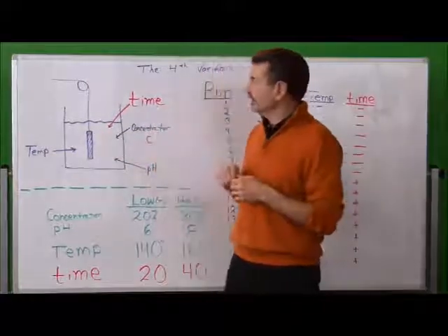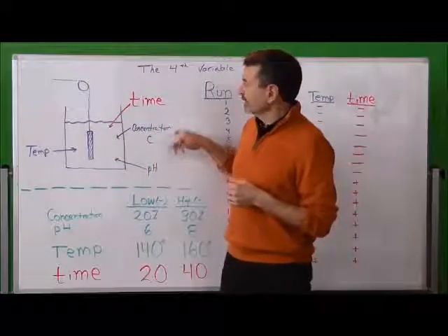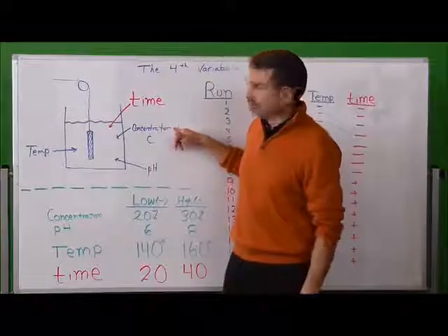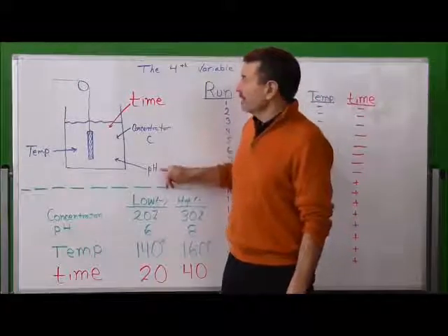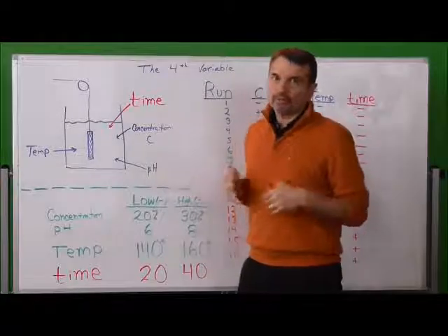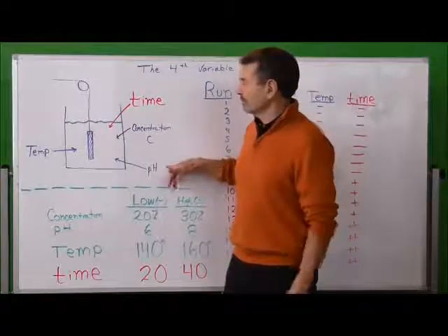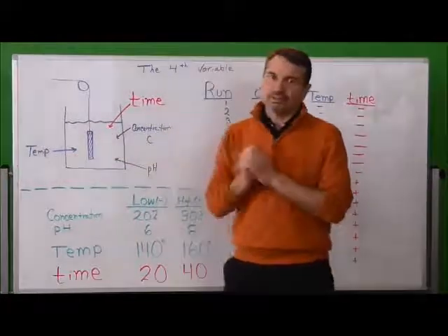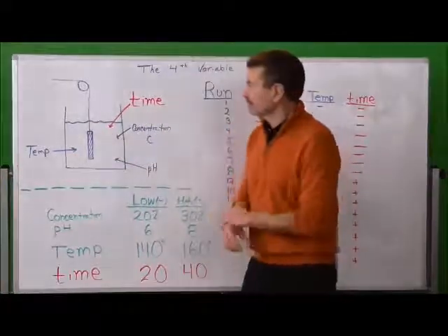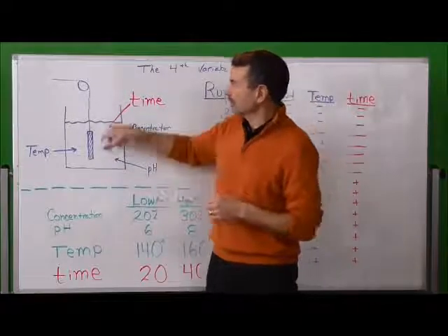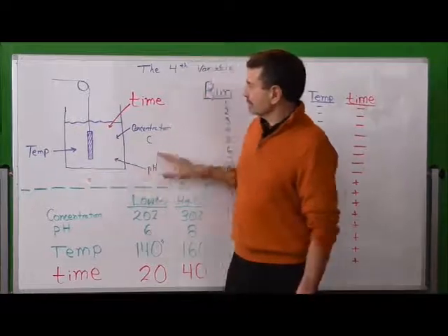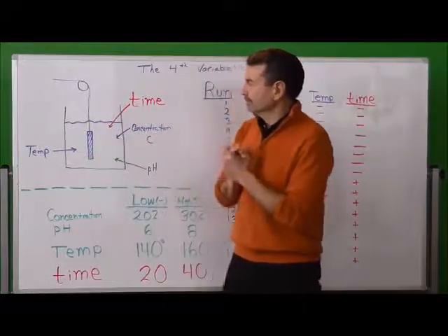When we did it the first time through, we looked at the concentration, or the percent, the pH level, which was primarily driven by the type of water being used in the process, and the temperature. There was actually a heating element inside the process, so you could regulate the temperature it was cleaned at. We originally looked at those 3 variables: the pH, the concentration, the temperature.